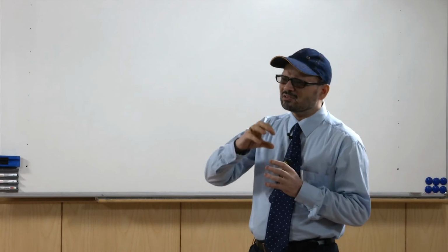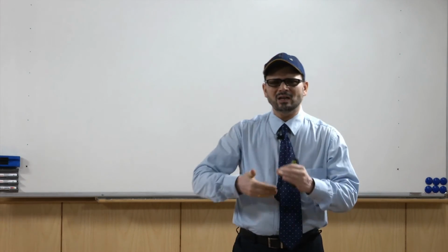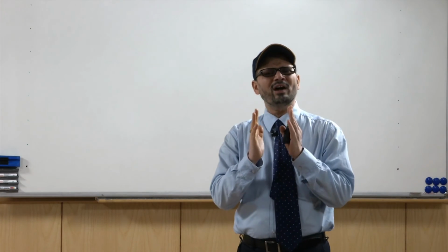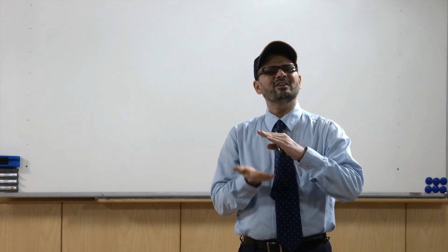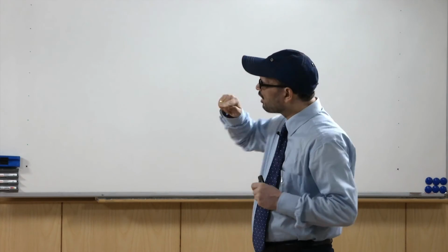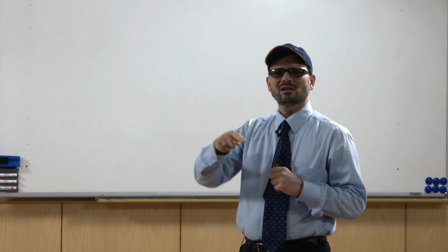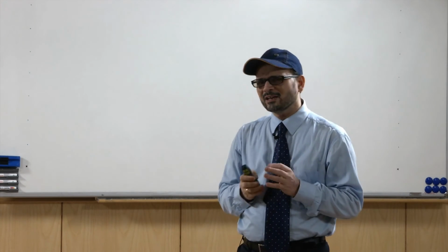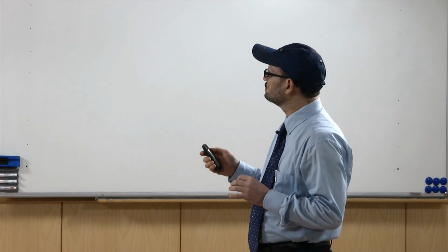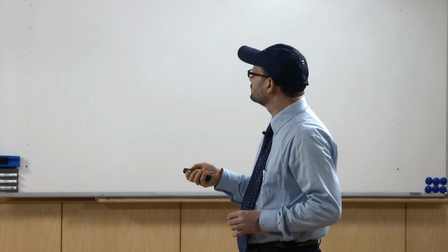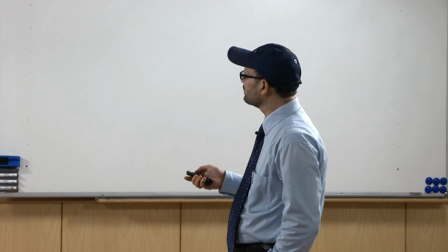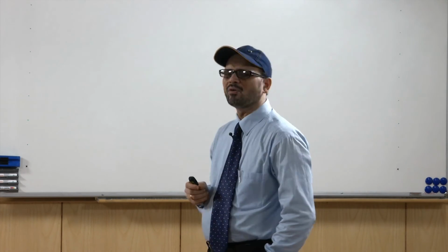So, what happens, there is formation of spherical particles, and being an alloy it will try to have dendritic arms, but because of the continuous stirring and agitation these dendrites are broken. So, ultimately because of the shear the dendritic structures are gone and the non dendritic type of structure is formed.